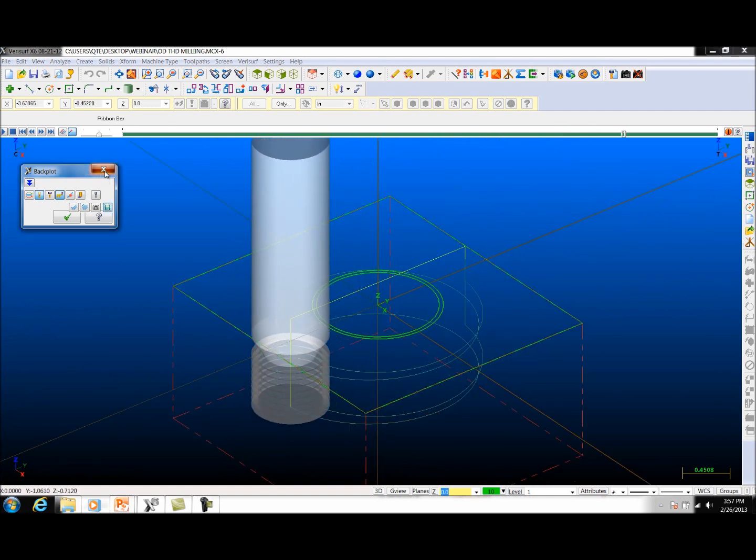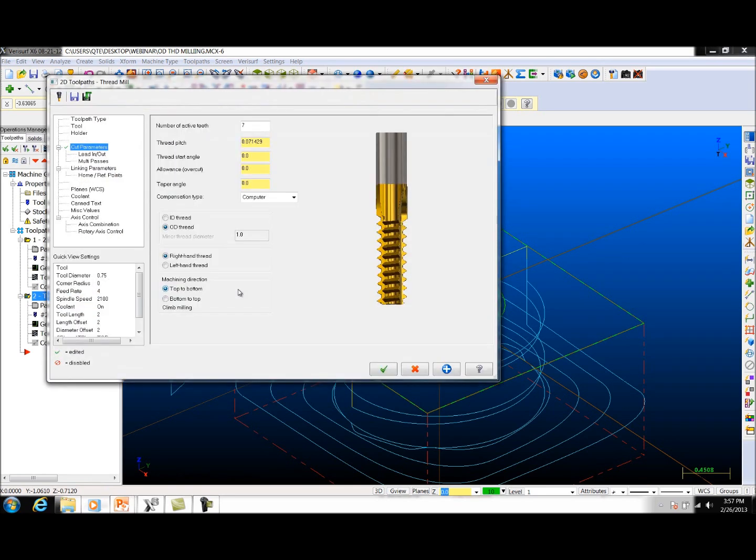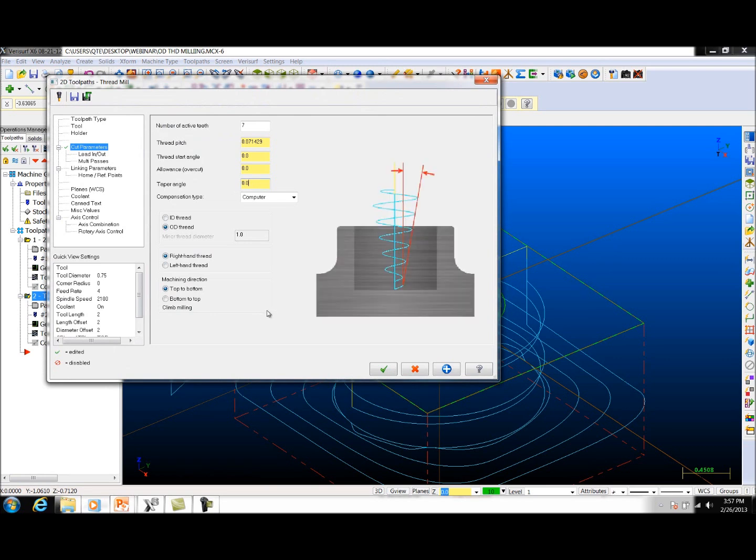If this is a tapered pipe tap, the taper angle right here. This is a decimal of degree, 1.79. The taper is usually 1 degree, 47 minutes, and 24 seconds, which you have to type in as a decimal of degree, which comes out to 1.79. That's what this angle wants. Makes like a tornado.